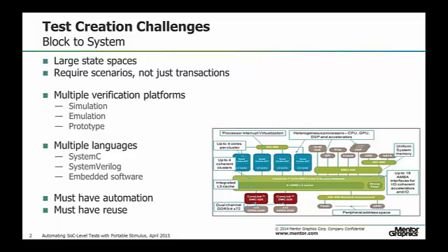Most of our users designing SoCs today don't use simulation alone. Typically we see usage of different verification platforms along the flow. People start maybe using something like System C for early prototyping. They move on to traditional RTL simulation, emulation, prototyping, and even post-silicon verification. The verification environment has to address all these different phases.